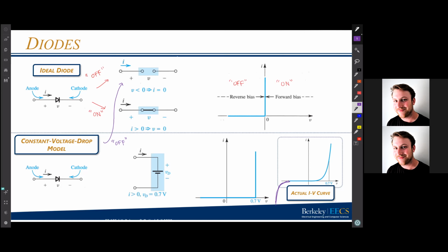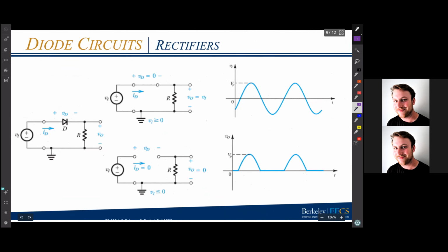With all of these models, it's important to understand that we are taking something new and nonlinear, and turning it into a linear device with models that we know, things like a short circuit or a voltage source. There's nothing special about these models. So once you replace the diode with its model, don't worry about whether it is a diode. Just analyze the circuit, trusting your instincts and what you know about the model. Oftentimes students get confused, thinking there might be some exception to the rules they've learned. But no, that's the whole point of the model: we can stick to the things we know, even when we're solving new circuits.